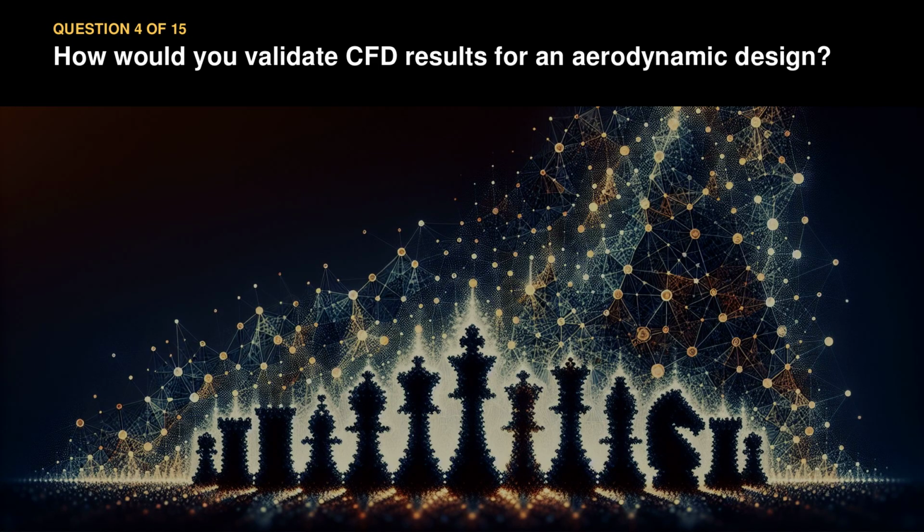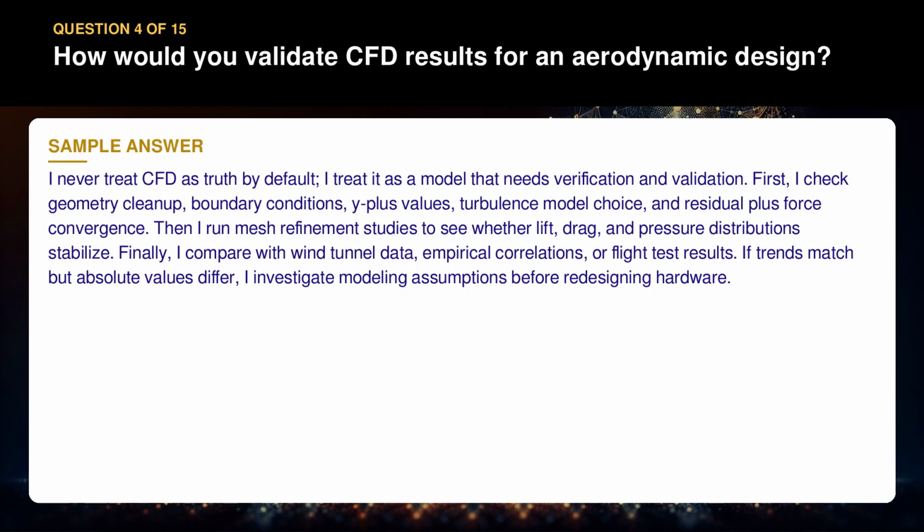Question 4. How would you validate CFD results for an aerodynamic design? I never treat CFD as truth by default. I treat it as a model that needs verification and validation. First, I check geometry cleanup, boundary conditions, Y+ values, turbulence model choice, and residual plus force convergence. Then I run mesh refinement studies to see whether lift, drag, and pressure distributions stabilize. Finally, I compare with wind tunnel data, empirical correlations, or flight test results.